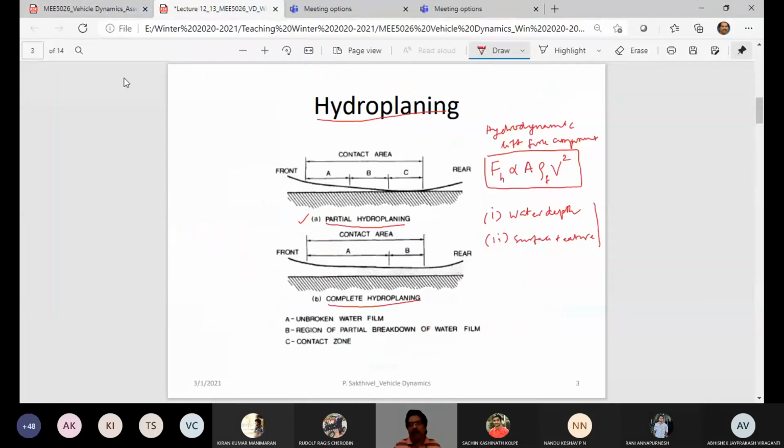This road surface is a common road surface. When you look at it, you would see its influence. We will see what will happen with different road surface influences. And water depth is the depth from the top of the water surface to the bottom. If it is of this type of road surface texture, the water will fill between the voids of the road surface. So the voids present there also help the water to go away. So these are the 2 parameters that come from the road. And similarly, you have parameters that come from the tire. Those are called tread pattern. So the type of tread pattern is going to influence hydroplaning.